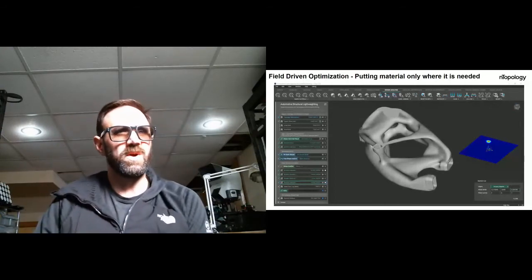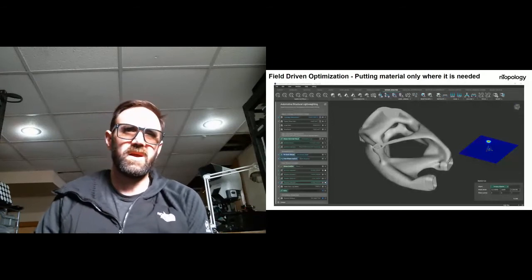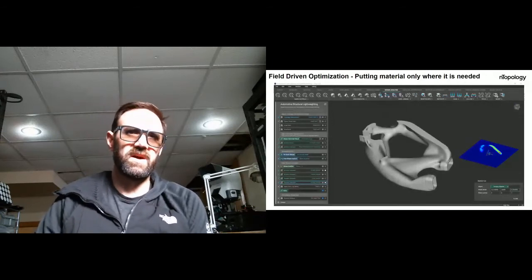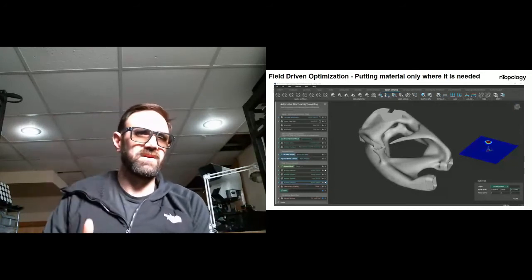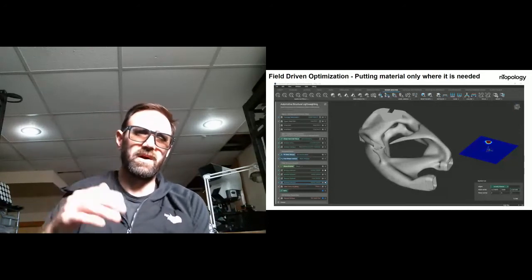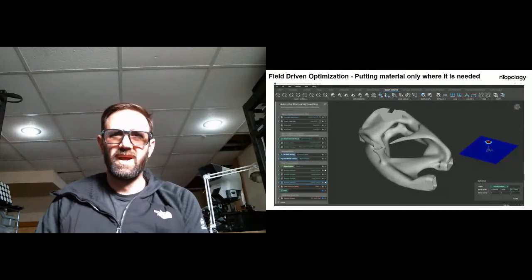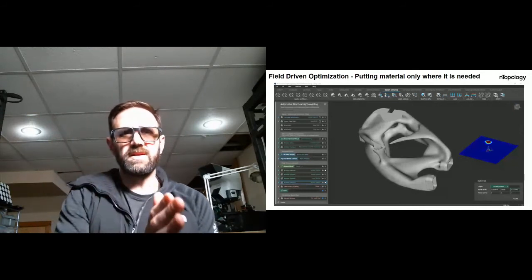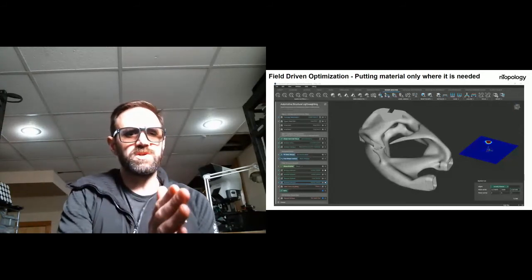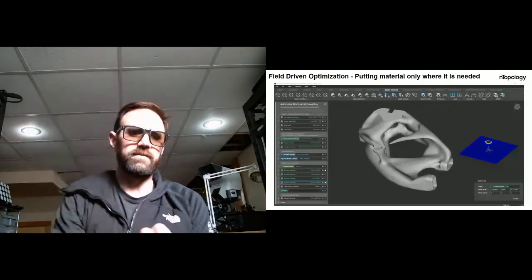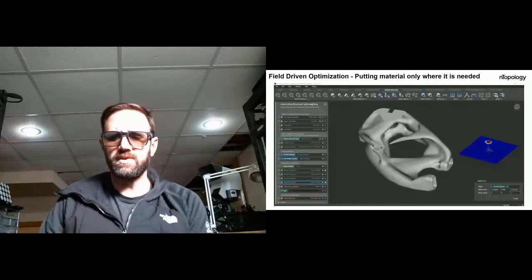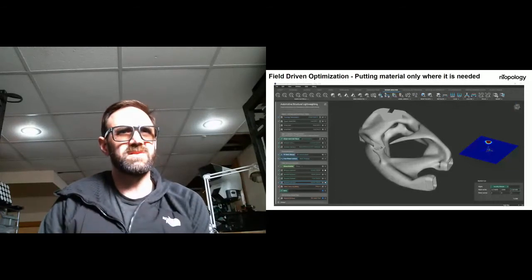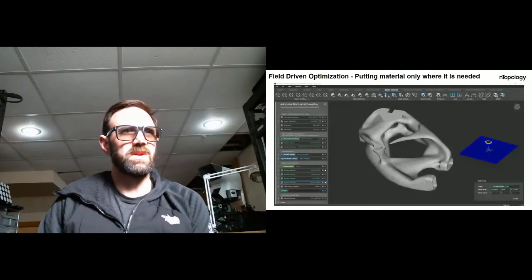And so we went from an initial mass reduction of 80% with the topology optimization, and we're able to shave another 8% of the weight off of that part based on the original design volume. And then more succinctly, from the original top op, which was a solid part, with that shelling we were able to cut weight 24% from those two pieces. So really able to cut weight.